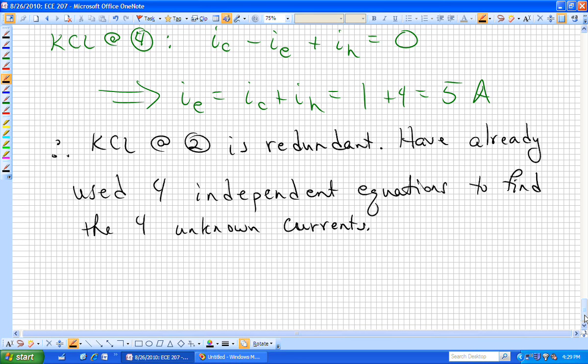As long as you're consistent with the individual equations that you're writing, you're okay. In one KCL, in is positive, and in another KCL, out is positive. As long as you don't magically change the sign of I sub A itself, you're okay.